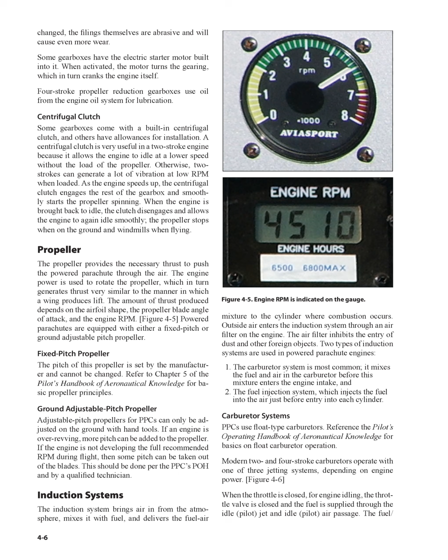Some gearboxes have the electric starter motor built into it. When activated, the motor turns the gearing, which in turn cranks the engine itself. 4-stroke propeller reduction gearboxes use oil from the engine oil system for lubrication.